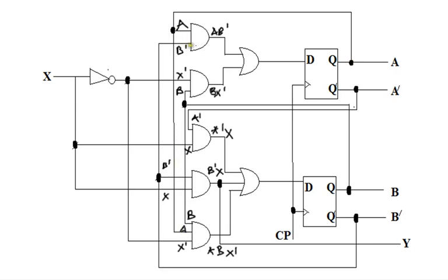But if you look at the other inputs, tracing it will lead us to this point, which is B prime. So I have B prime entering here and the same B prime entering here. Then if you come to this gate, one of the inputs is from here. You see, this is external input X, and we pass it through an inverter. This should be X prime. But the other one, look at it, it is coming from B here. So doing this, I trace all the origins of the inputs.